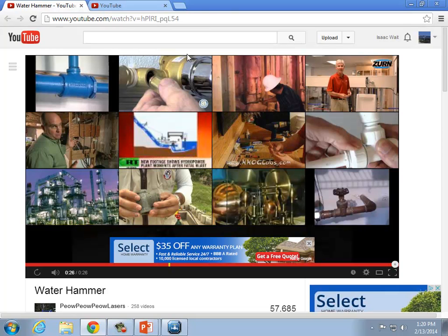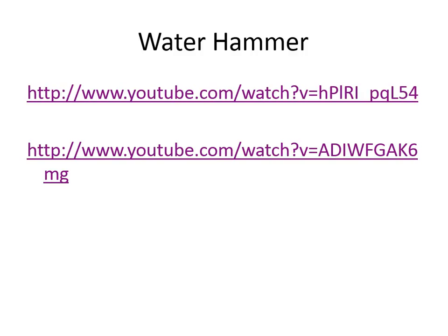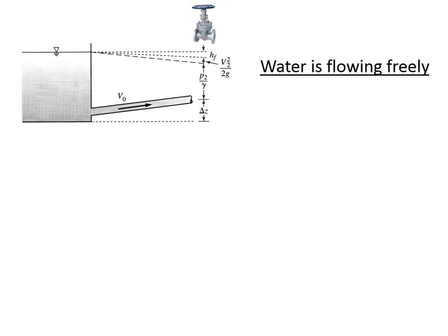In the case of that second video, it was someone who was running their dishwasher, and then they walk over towards the water heater, and that's where the sound of the pounding was coming from as they were using the dishwasher. Now, the phenomenon of water hammer has to do essentially with how quickly valves are being closed. And let me walk you through what causes that pounding sound, and it's more than just an unpleasant sound. It can actually destroy equipment.